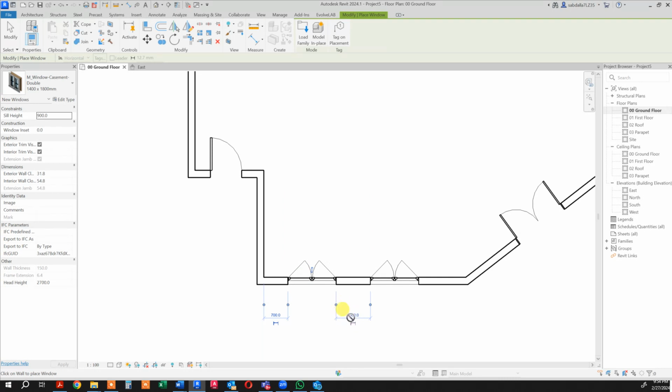Now you notice that this is called a temporary dimension in Revit. So let's say you want 1 meter here, not here. I could just click on the number and type 1000. The door will be shifted. Now you could see the dimension. If I click here, this will become a permanent dimension, but it's a temporary dimension. I don't need to set it now. So I'm gonna press Control Z to get rid of them.